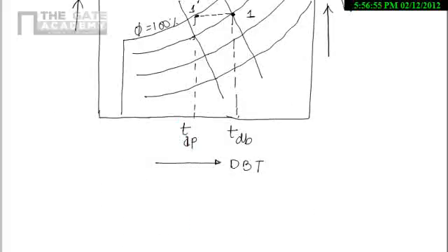So for obtaining dew point temperature, we have to move parallelly along the axis of dry bulb temperature, and the point where the line will intersect with phi equals to 100%, means relative humidity 100%, at that point we have to read the reading on the dry bulb temperature axis. It's the dew point temperature.